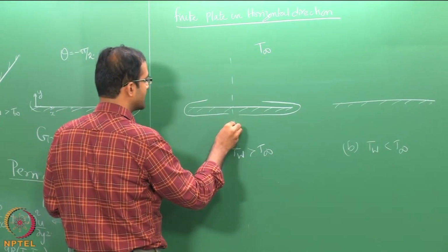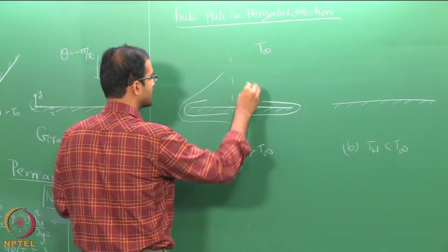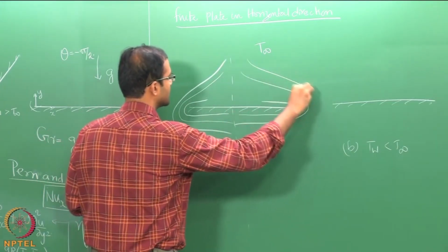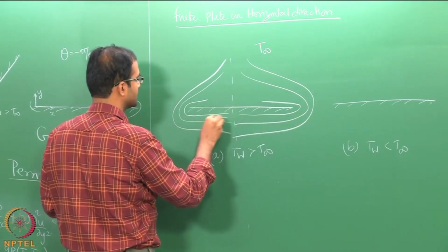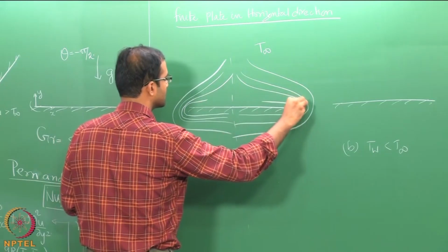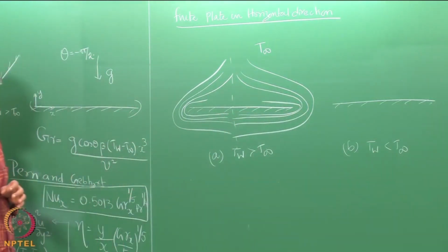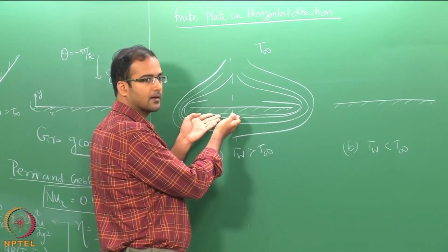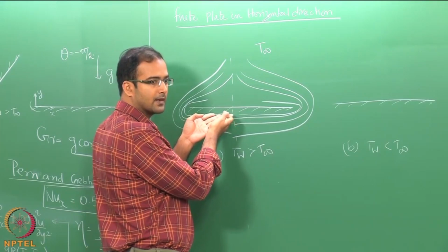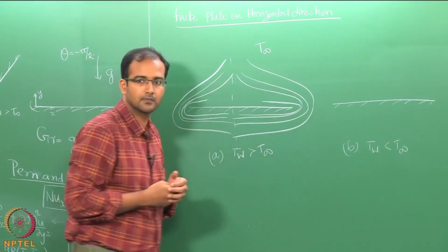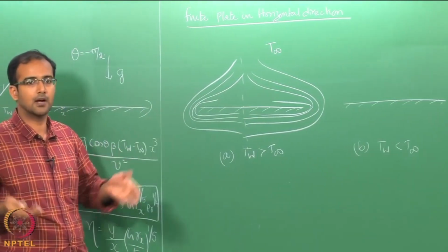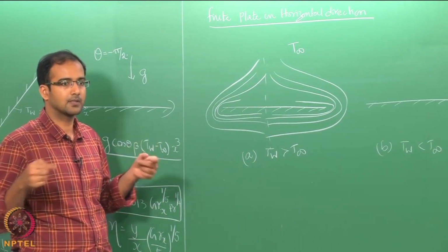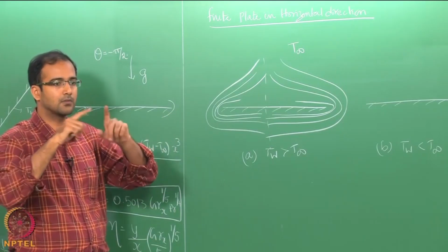So, you will generally see that this is the kind of pattern that you will end up with. Okay. So, the hot fluid which is in contact with the plate at the bottom surface will now have a tendency to escape through the edges. If this was infinite, this hot fluid would just be staying there, it can never rise up, but due to the finite length, the edge effects now cause the flow of the hot fluid to rise up.